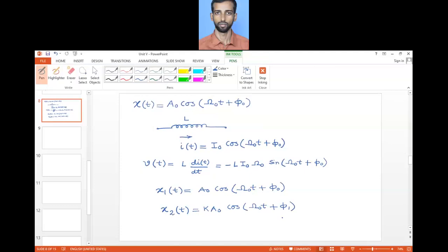In that case, it will be easier for us to visualize the signal if I observe it from a completely different perspective altogether. Here the amplitude is multiplied by some factor k, but the phase is not multiplied by the same factor or by some other factor. Rather, the phase is augmented by some amount, some plus or minus. It's not simply multiplication. We have studied LTI systems, linear time invariant systems, where we have three different properties: the additivity property, the homogeneity property, and the time invariance property.